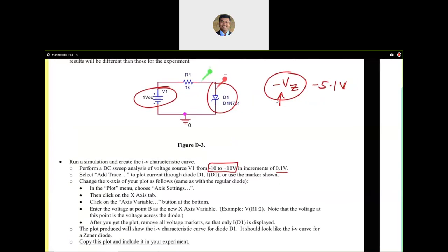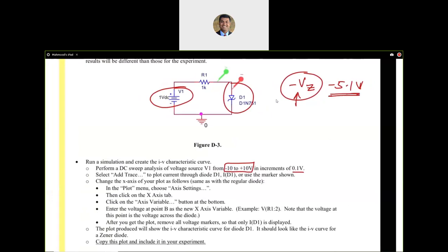So my answer to that is, if you're not able to explore negative 5.1, and if for some reason your simulation say stops at negative 5.2 and you want to extend it a bit more, then what you can do is extend this simulation, the parametric sweep, to negative 30 to 30 volts in the same step size, 0.1. So by doing that small change, you will have the ability to go even slightly lower. Maybe not 5.2, but maybe 5.1 to something. So even beyond that.